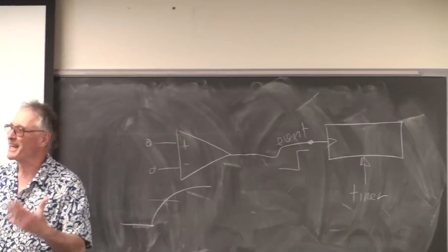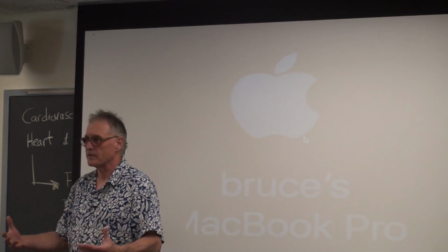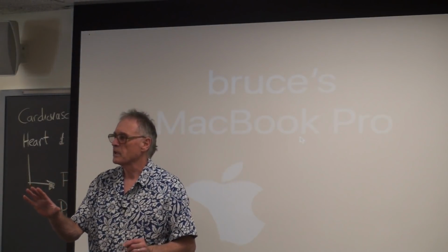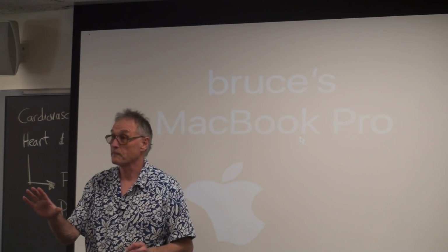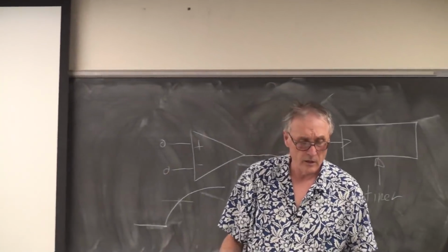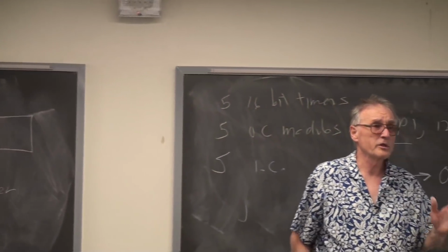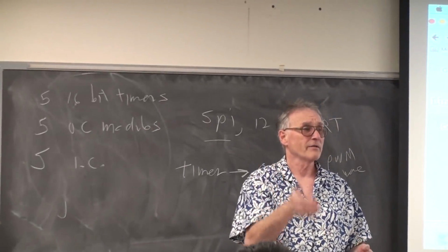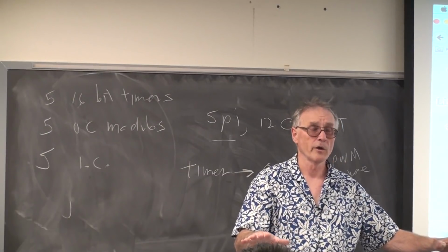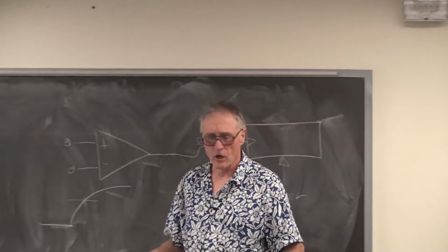So you've got this gigantic toolkit of stuff in the CPU. You've got all these output compare channels. You've got these input captures. You've got these timers. Certain timers, they're not orthogonal. Some timers have special functions. Timer 3 can trigger the A to D converter automatically. So timer 3 can talk directly to the analog to digital converter, which can talk to the DMA controller, which can grab the ADC data and put it in memory. So you can have a timer ticking away, grabbing data from the analog converter and putting it in memory with no code executing. No interrupt service routines, no code. That's cool. It's also confusing. That's why we need to talk about it.